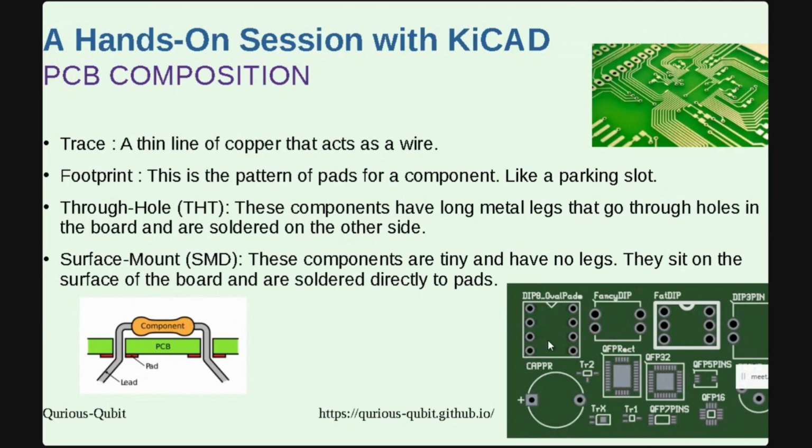You can see these are the footprints. They are basically like a parking slot. They give us the outline of the component so that you have a defined dimension that fits the component that's available in the market. So you design with practicality, not just theory. That's where understanding of PCB really comes into play when you're trying to design a circuit in KiCad. So that's what our footprint does.